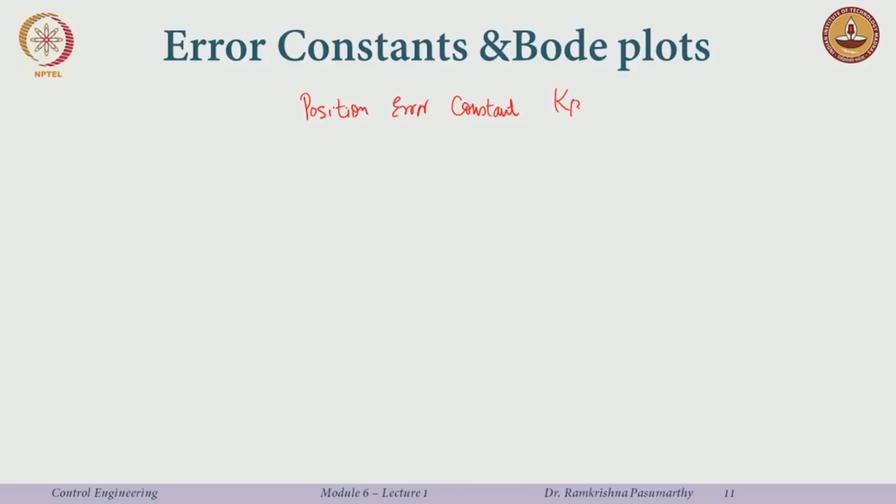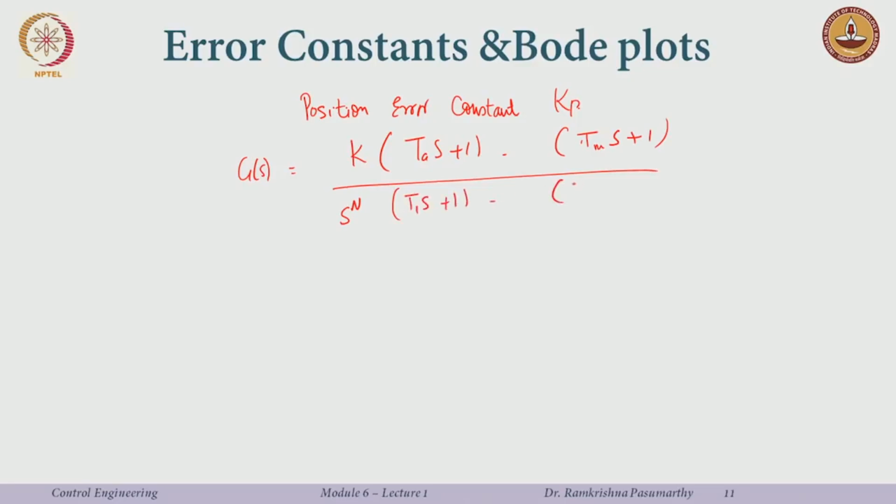Kp, right. Okay, how does a typical transfer function look? Well, if I write it in the sinusoidal form, I have k, I have the set of zeros, say T some number m, over some poles at the origin, and I will have T1 s plus 1 and some Tn s plus 1, small n, right. And I can write this as the sinusoidal transfer function just by substituting s with j omega, right.